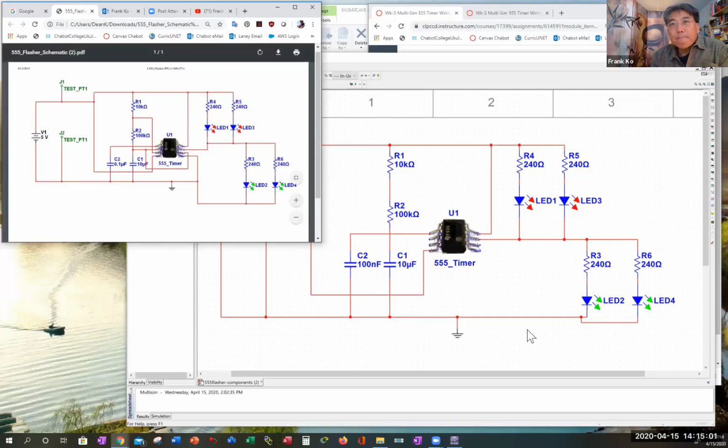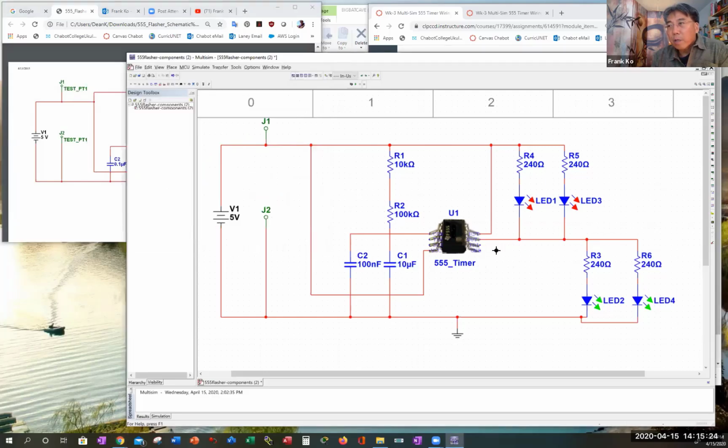Next, there happens to be a wire that connects all of these on the negative side of this. Something from this rail has to come up and connect to the fourth pin on the right-hand side of this chip. See this wire right here? I have to make a connection to my ground wire. So I will come up here, click, come over, click, come down, click.